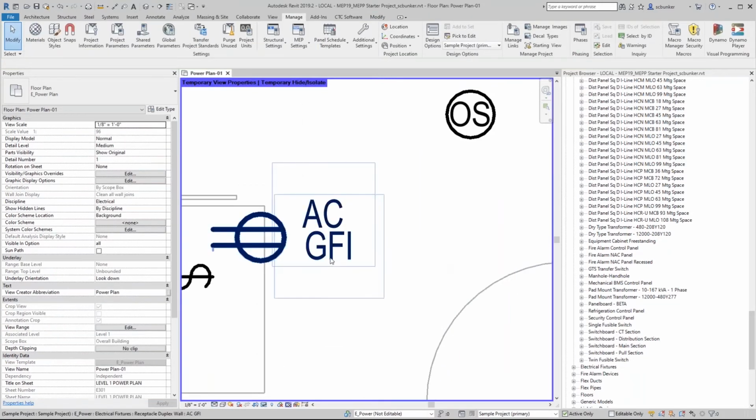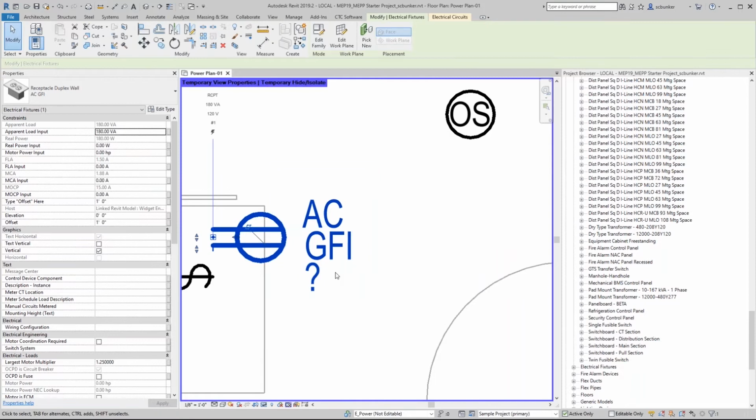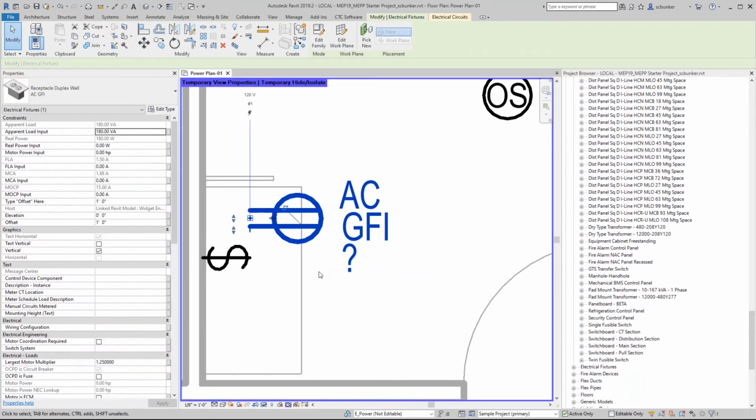And then we have built-in labels. If you have worked in Revit, you know that if you try to tag something that doesn't have the data in the tag parameter, it'll show a question mark. It'll just have this big question mark. And so the tag all not tagged command can be difficult to work with in Revit when you're working with electrical fixtures.